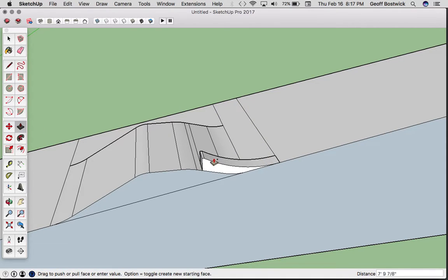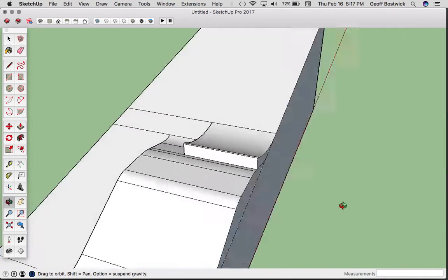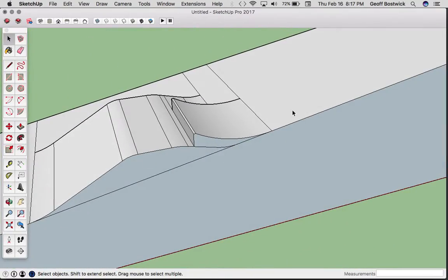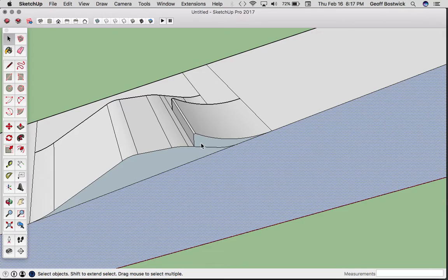Click once on this. We're going to go over, we were at 60 feet wide with a landing. Let's go over 40 feet wide with this. And then let's take this side and just move it over 20 feet. There's something that goes on with these reverse faces, they're called. So this is white, and then this is kind of bluish.